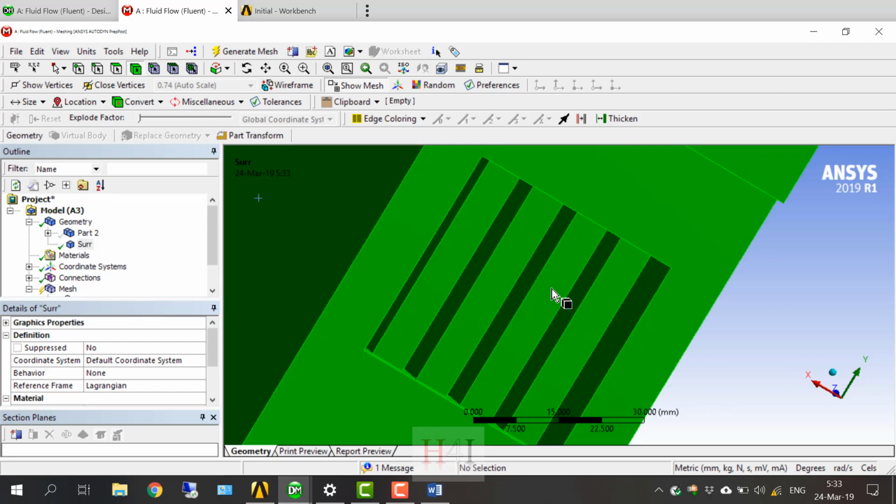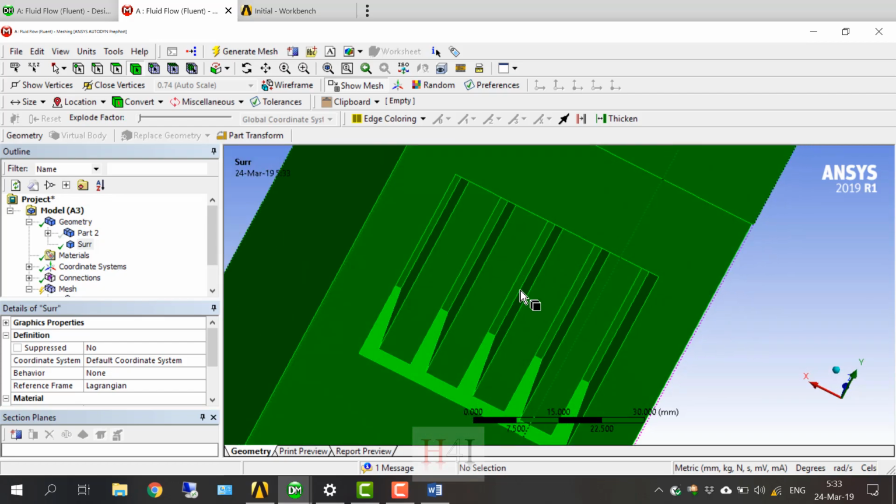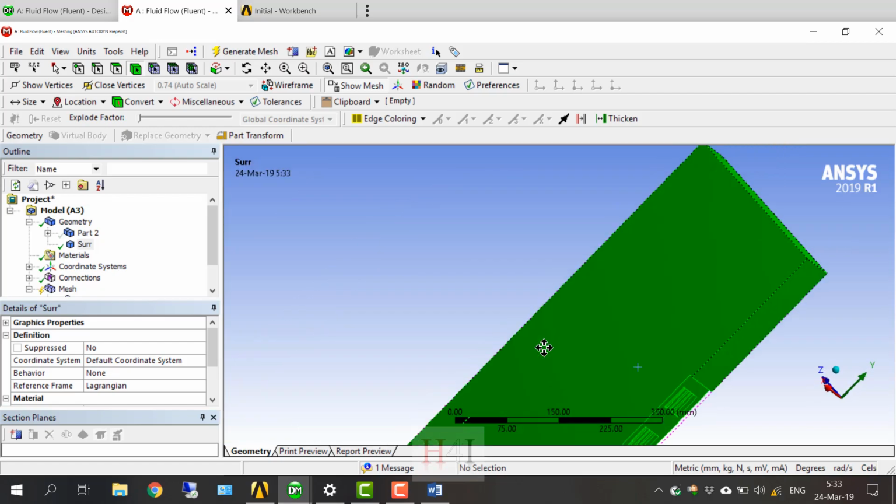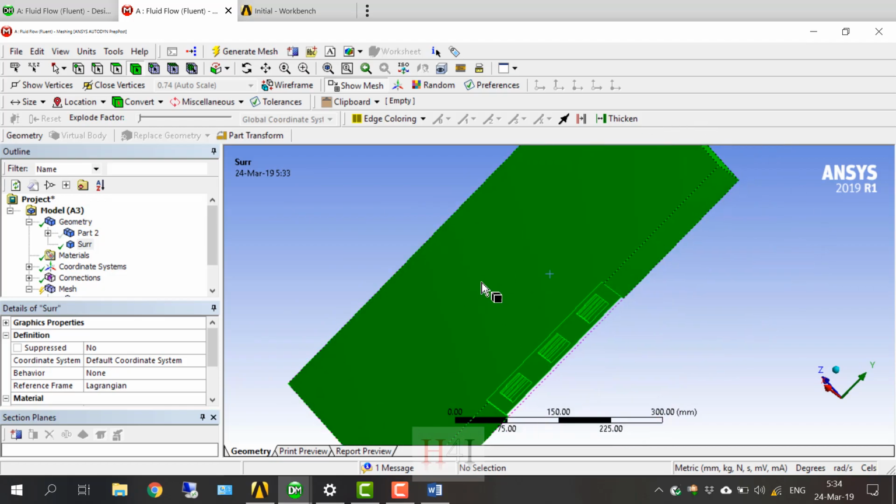Well, as you can see, this is the space between the fins of the heatsink. So these 5 regions can be treated as single bodies and swept. Use a sweep with it, and the same for the big space above. I will not divide it. Multizone will do it. I say multizone, do it for me.